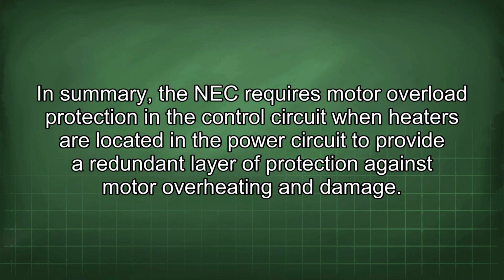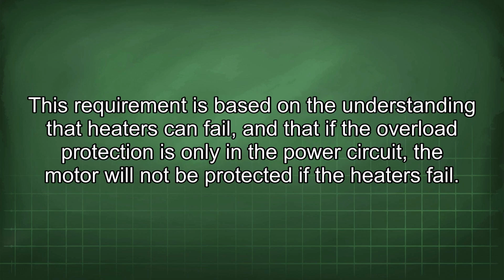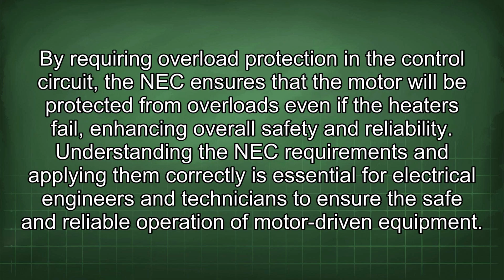In summary, the NEC requires motor overload protection in the control circuit when heaters are located in the power circuit to provide a redundant layer of protection against motor overheating and damage. This requirement is based on the understanding that heaters can fail, and that if the overload protection is only in the power circuit, the motor will not be protected if the heaters fail. By requiring overload protection in the control circuit, the NEC ensures that the motor will be protected from overloads even if the heaters fail, enhancing overall safety and reliability.